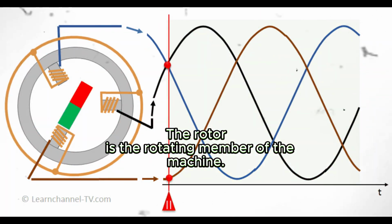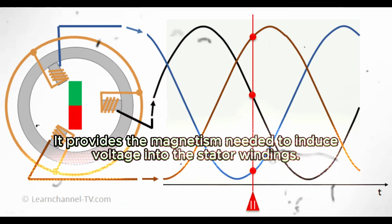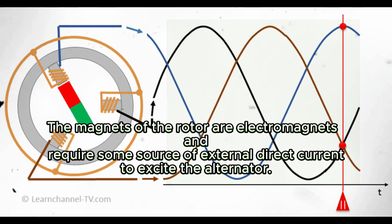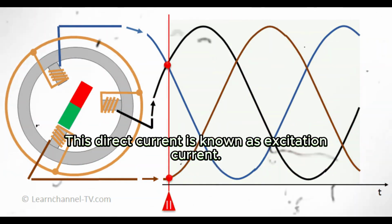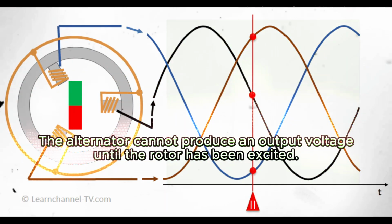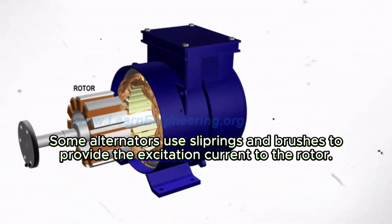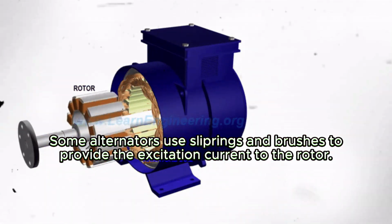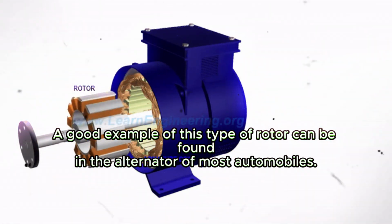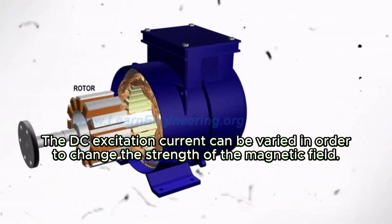The rotor is the rotating member of the machine. It provides the magnetism needed to induce voltage into the stator windings. The magnets of the rotor are electromagnets and require some source of external direct current to excite the alternator. This direct current is known as excitation current. The alternator cannot produce an output voltage until the rotor has been excited. Some alternators use slip rings and brushes to provide the excitation current to the rotor. A good example of this type of rotor can be found in the alternator of most automobiles. The DC excitation current can be varied in order to change the strength of the magnetic field.